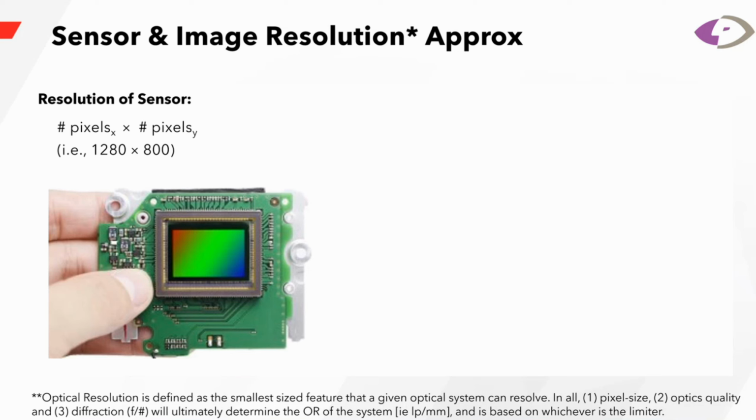And we can, of course, use a smaller resolution in high-speed cameras. We would refer to this resolution as the active sensor area. To determine the active sensor area, we look for the pixel size in our specification data sheet, and we multiply that by the number of pixels in the X and Y direction. This is important for choosing the optics in your application.